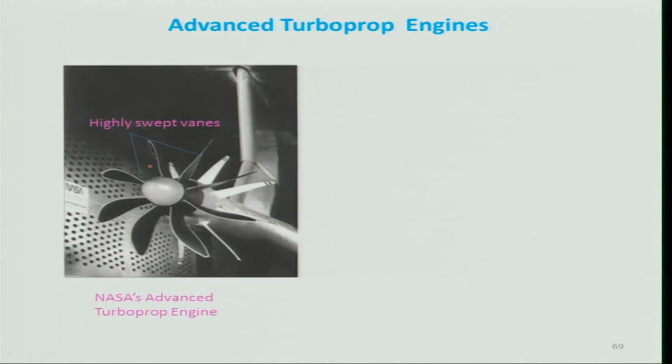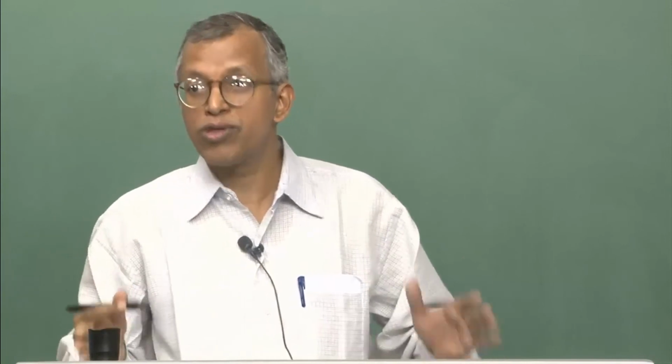because when you reduce this speed, then the gearbox will be very big. Suppose your engine is operated at 50,000 RPM, you will have to bring it to 2000 RPM. It will be a gear ratio of 25:1. So, the gearbox will be much bigger, because the power level of the engine will be very high. In this case, not like your automobile engine, some few kilowatts, it will be of the order of megawatts. Therefore, when you reduce the RPM, you will be reducing the gearbox weight as well.